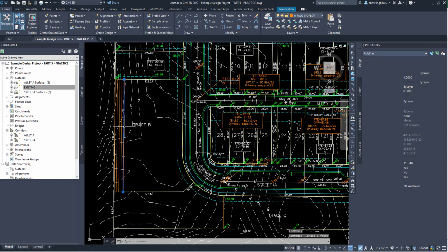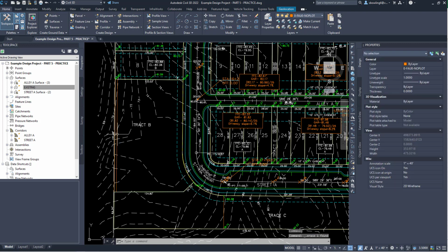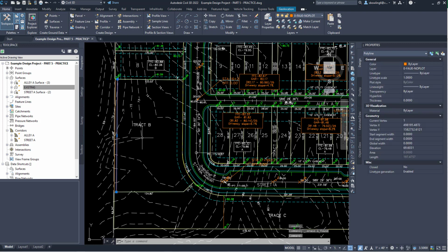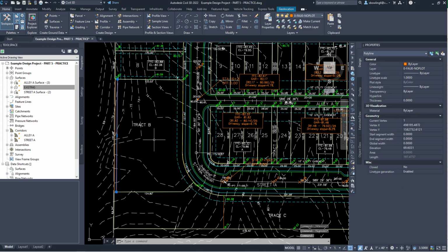I typically have my pond no more than 5 feet deep. And if I'm tying and assuming this is a 71, so here's my 70, I'm assuming the bottom of my pond is 71. So this would be 72. I've got to come up and then come back down. So if the bottom of the pond is 70, the top of bank is going to be 74, 75. Okay, or 73, 74 if I only want 4 feet deep. So we're going to try 4 feet deep.